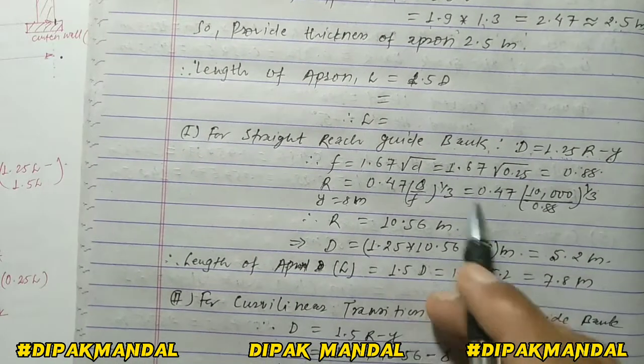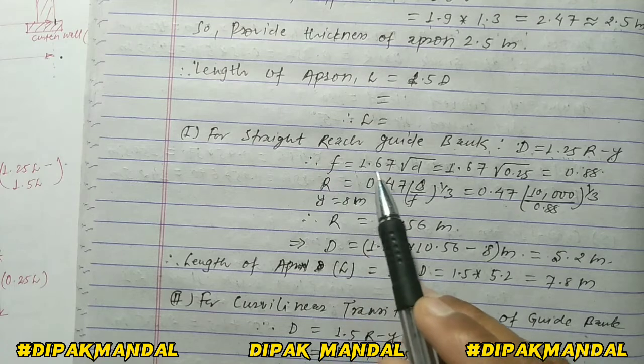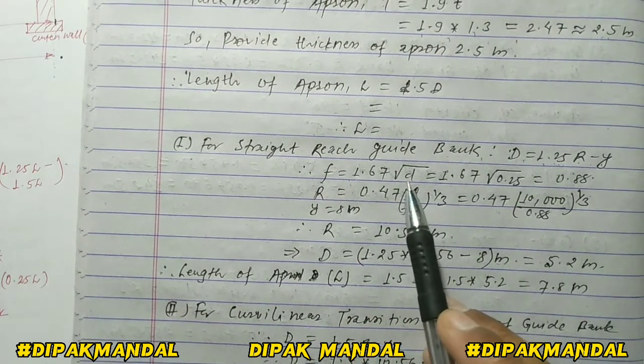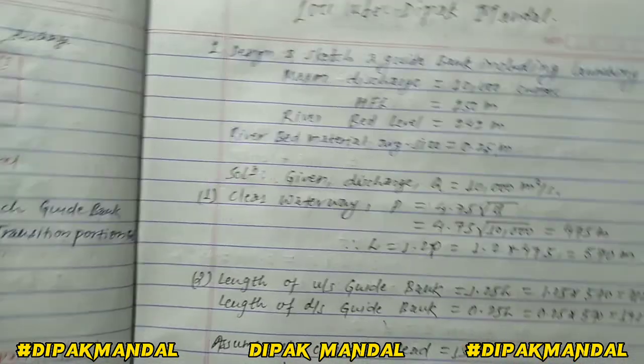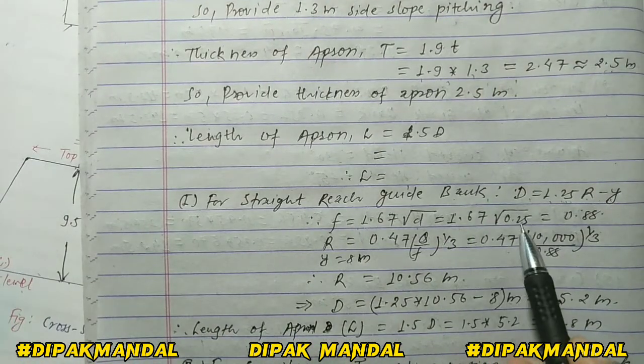Okay, and now we can calculate the value of f equal to 1.76 root under d. And what is d? d is the size of silt particle. Okay, and the size of silt particle in the given question is equal to 0.25 meter. So we just use this value, 0.25 meter.